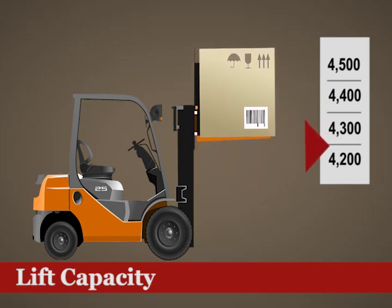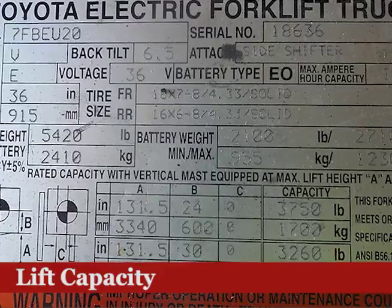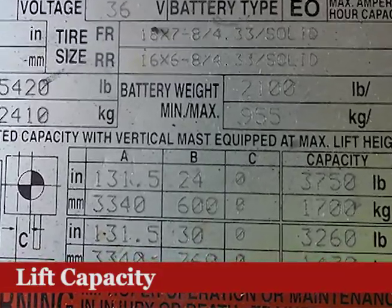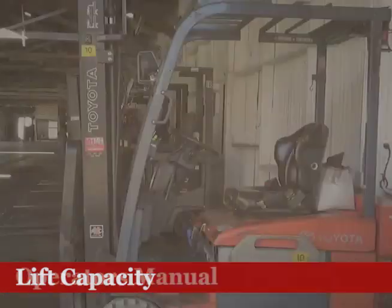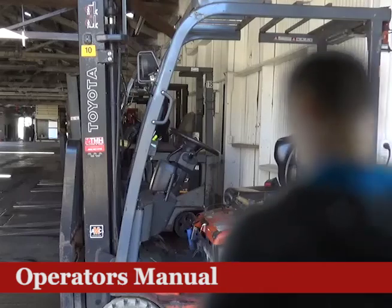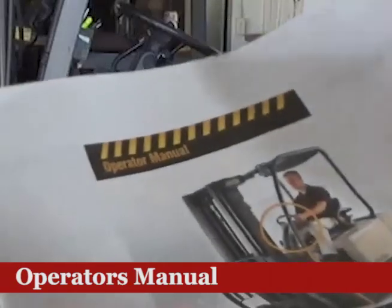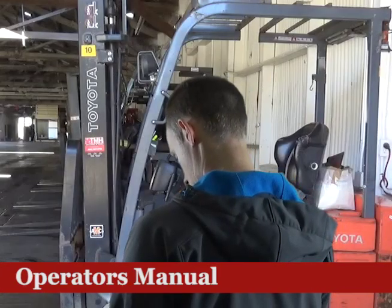Some forklifts will have different distances listed for lift capacities, and some will just have one maximum height. Make sure you are familiar with the information on the data plate, and remember, the lifting capacity may be lower, depending on the characteristics of the load you are moving. All of these parameters can be found in the Vehicle Operator's Manual, which must be kept on the forklift. Make sure you are familiar with the contents of this manual. If you follow its guidance, your powered industrial truck will remain within the stability triangle, and more importantly, you will be kept safe.